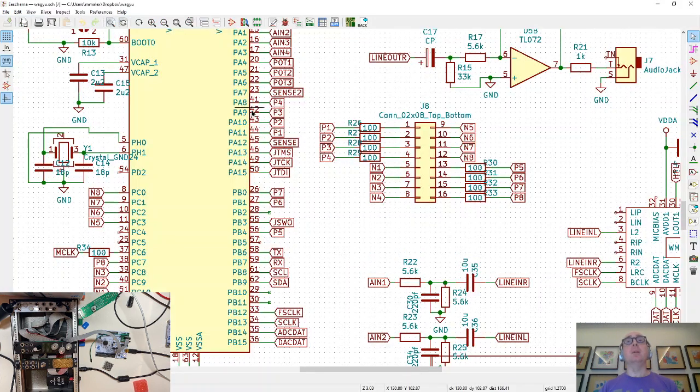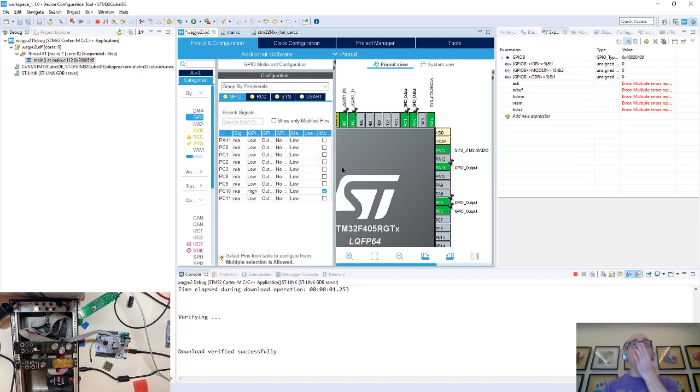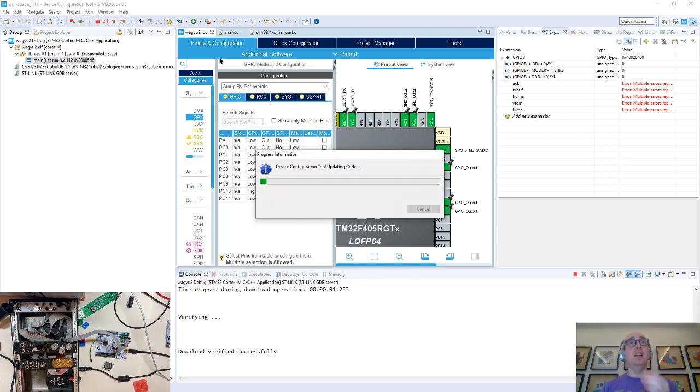Fine. And let's do P1 to the corresponding pin, which is P1, which is pin 44, PA11. Here it is. I'll set you up to be a GPIO output, and you are going to be low, which means it should, if we're lucky, just light up one LED. Should we find out? Hit save.